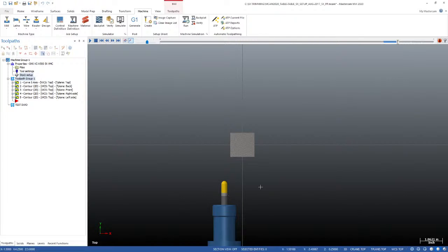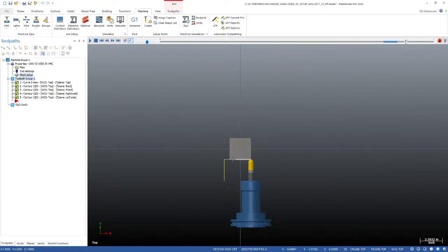That flip in the software is going to come with a tool change. The old operation is going to retract and go home. It's going to change tools, and the new toolpath is going to approach the part and make its cut. But that doesn't really show properly in the machine simulation, because again, it's a default thing.